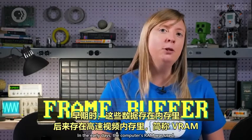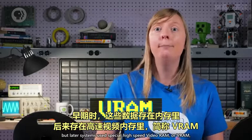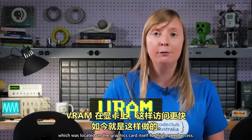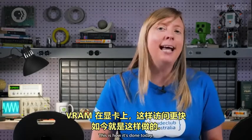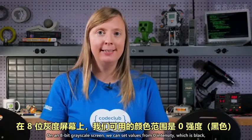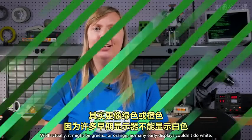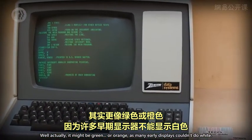In the early days, the computer's RAM was used, but later systems used special high-speed video RAM, or VRAM, which was located on the graphics card itself for high-speed access. This is how it's done today. On an 8-bit grayscale screen, we can set values from 0 intensity, which is black, to 255 intensity, which is white. Well, actually, it might be green or orange, as many early displays couldn't do white.